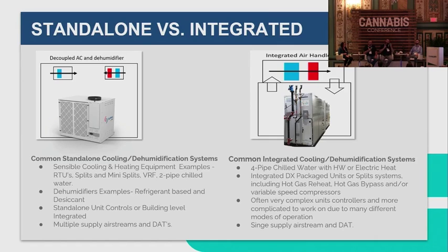No, I think that's a good point, and a subtlety that maybe we can't get into on the panel, but if anyone's interested, we can talk about it afterwards. Sometimes you have to oversize with an integrated system. We found you have to oversize the tonnage in order to handle some of the lights-off evapotranspiration, and you can actually utilize both these strategies together to, quote unquote, right size your equipment. So you might be able to downsize your integrated machine, which is usually a more expensive machine, and supplement with some standalone dehumidifiers, and therefore get the best of both worlds, so to speak. So you're not overpaying, but you are hitting that relative humidity set point, and you're getting that latent capability that you're looking for out of your room to keep your cultivars exactly where you want them as far as VPD, temperature and humidity.